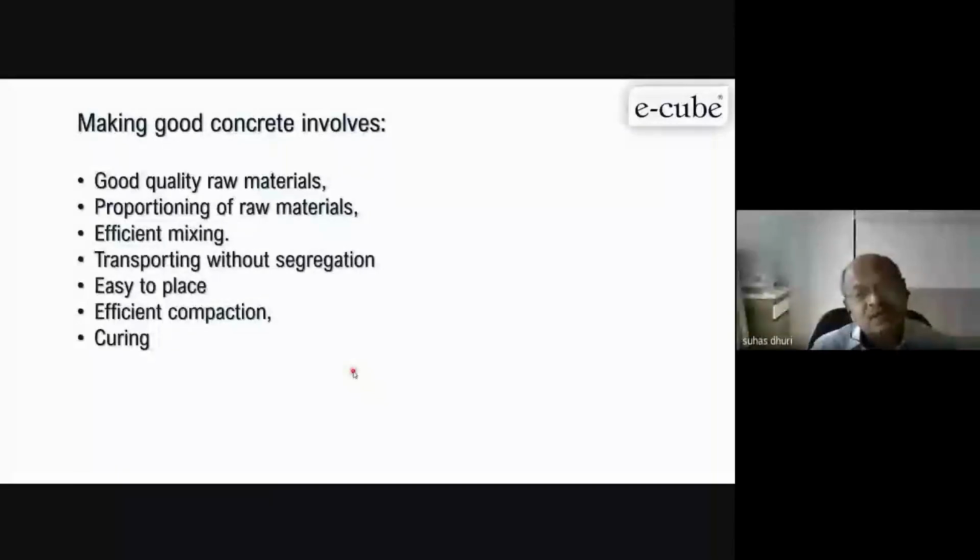So that is also very, very important, the selection of the mixer, or whatever available mixers are there, and how to get optimized mixing time. You cannot go only with the mixing time given by the batching plant manufacturer. The concrete technologist has a role: he has to work out the mixing time for his mix proportions.